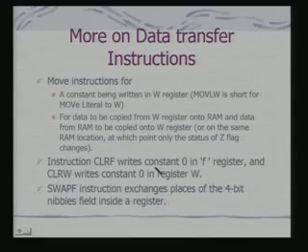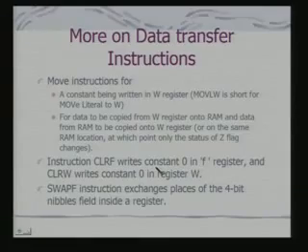So, now if we can summarize what we have seen in particular for byte oriented data transfer operations, then we have provision for writing onto the W register through immediate mode. That is, the literals can be copied to the W register.